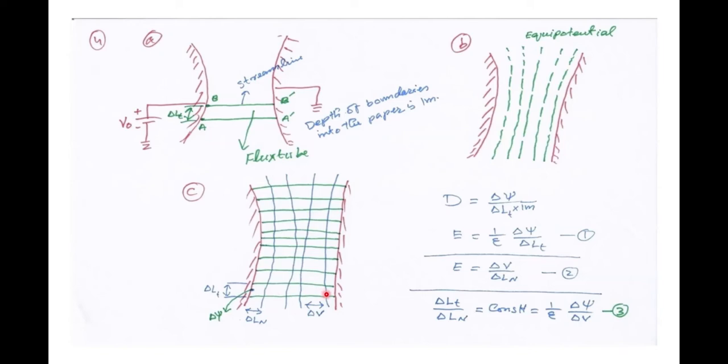That is how we divide the space between conductors into curvilinear squares. As the boundaries are not perfectly planar, the squares are not exactly similar to the squares in the case of planar conducting boundaries. That is why we call them curvilinear squares.